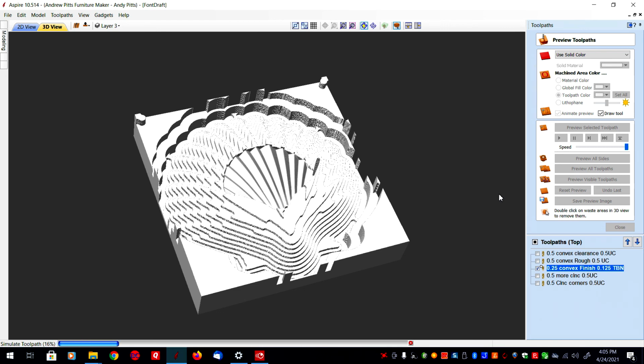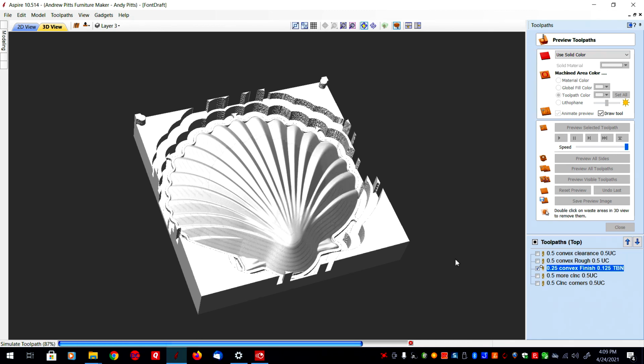I did an offset strategy instead of a raster strategy on this because I wanted to really be careful and be able to see what the machine was doing when it got very close to these blocks. If I'd started with a raster strategy, it would have started cutting, usually down the lower right hand corner, and that means the tool would have gone full depth for the very first cut. And I wanted to be able to watch and make sure things weren't going to hit. It's a whole lot easier to watch it creeping up on the edges.